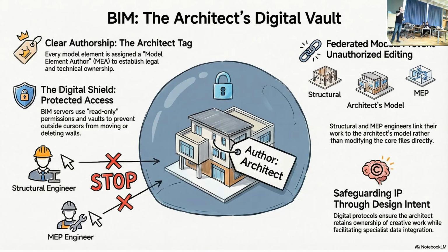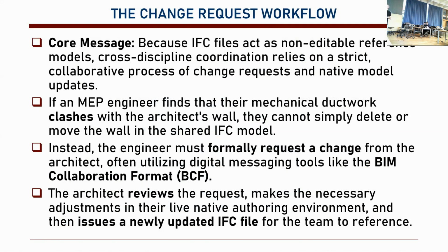So it's very similar. You don't want to give your Revit file because it has your objects, it has your own, let's say, intellectual property. But if you give an IFC model, it doesn't hurt. Okay, and then that IFC model basically allows us to create a reference point for cross-discipline coordination. Okay, so different stakeholders can work on that model and bring back their requests, okay? Because they can find the clashes, and then they request a change. And what we use there is the BIM Collaboration Format, BCF, okay? The architect reviews the request and makes changes, and then updates a new IFC file.